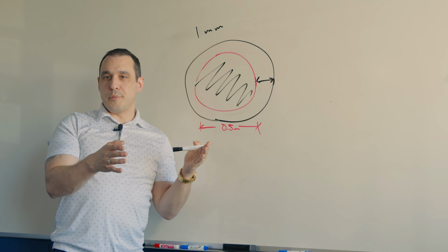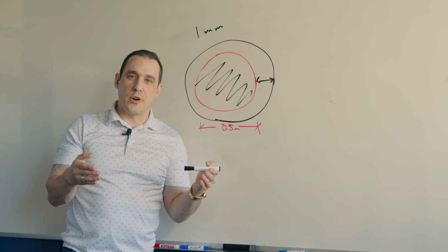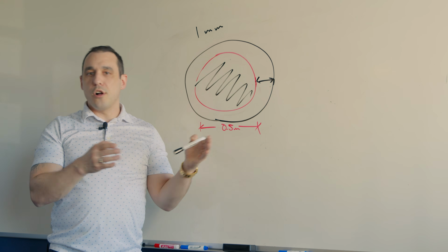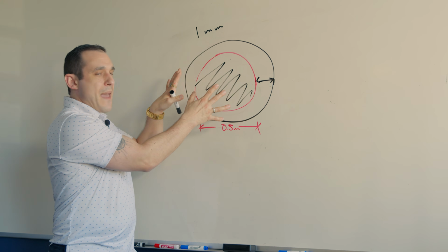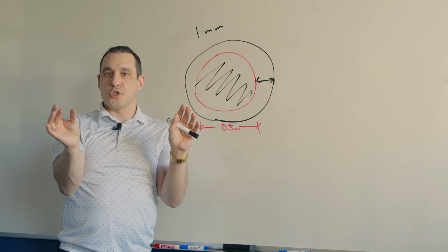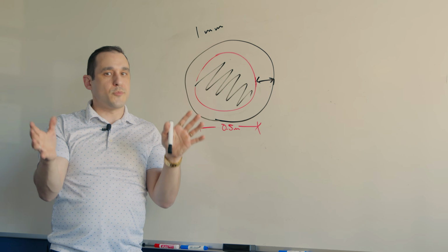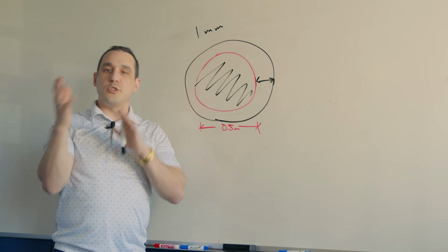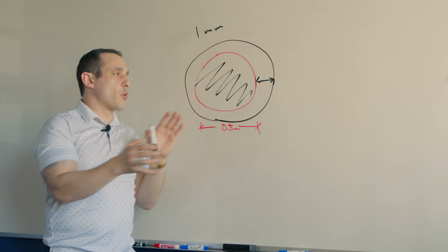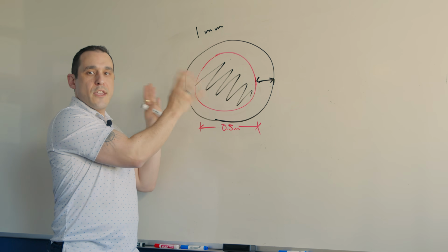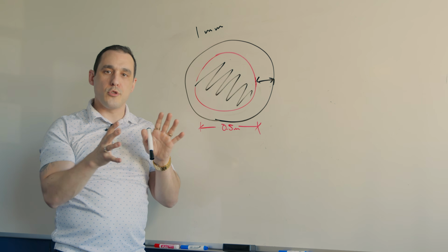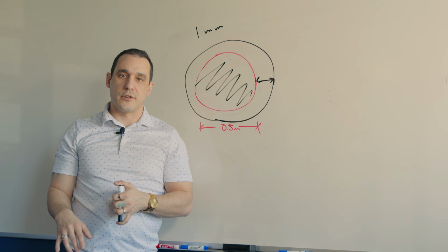So with a 1 millimeter pitch BGA, or possibly even a 0.8 millimeter pitch BGA, all you need to do is just set the right pad size, set a little bit larger solder mask opening, not too large but not too small, and then you'll be able to do dog bone fan out, and you won't have to worry about any of this stuff to ensure that you get a consistent copper exposure to the underside of the BGA for soldering.